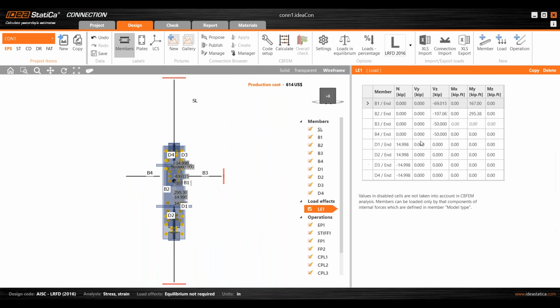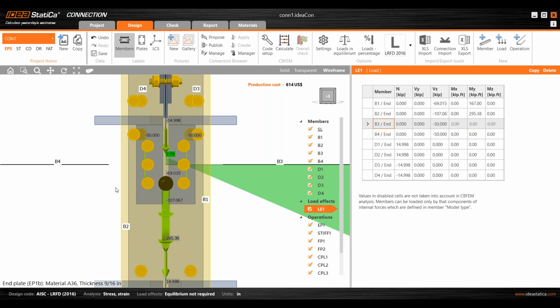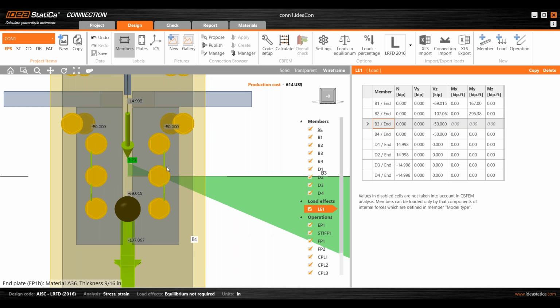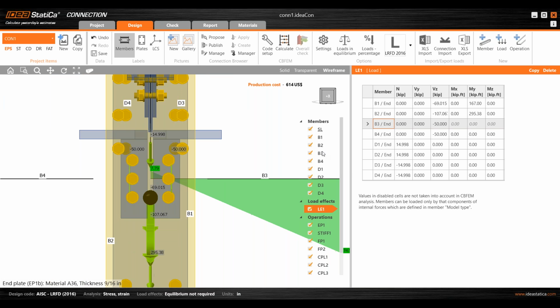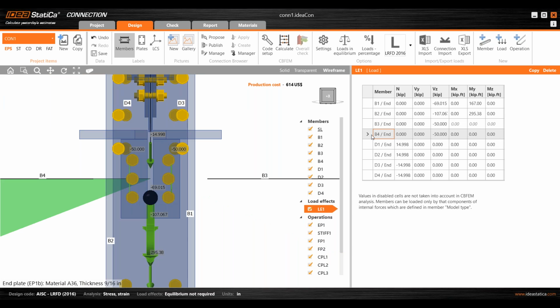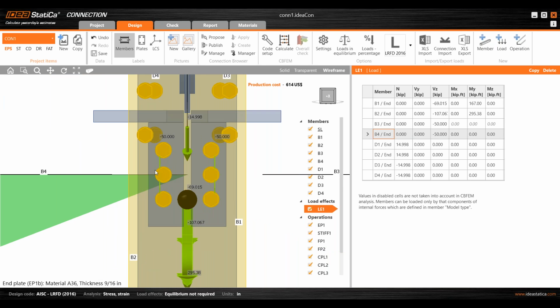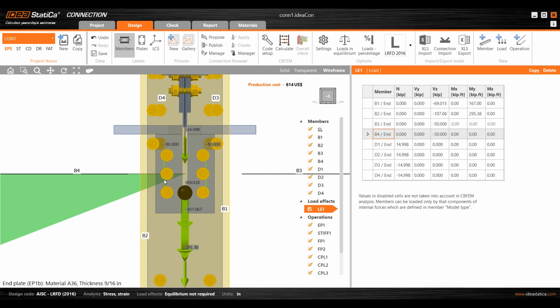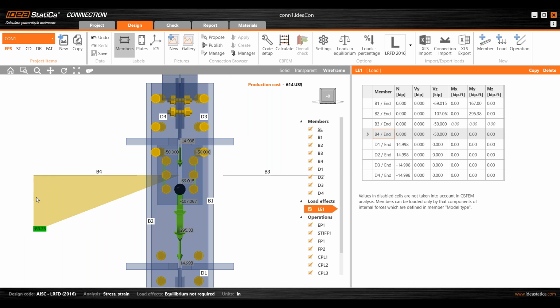And then if you go to the load effect, and then let's see this one. So this is creating the hinge into the bolts. And then if you go to the before, you will see that here it's having also a moment at the end of the beam, right? So the correct location of the force when you have only shear force in one member is where the hinge in real life will happen. In this case, the bolts, right?